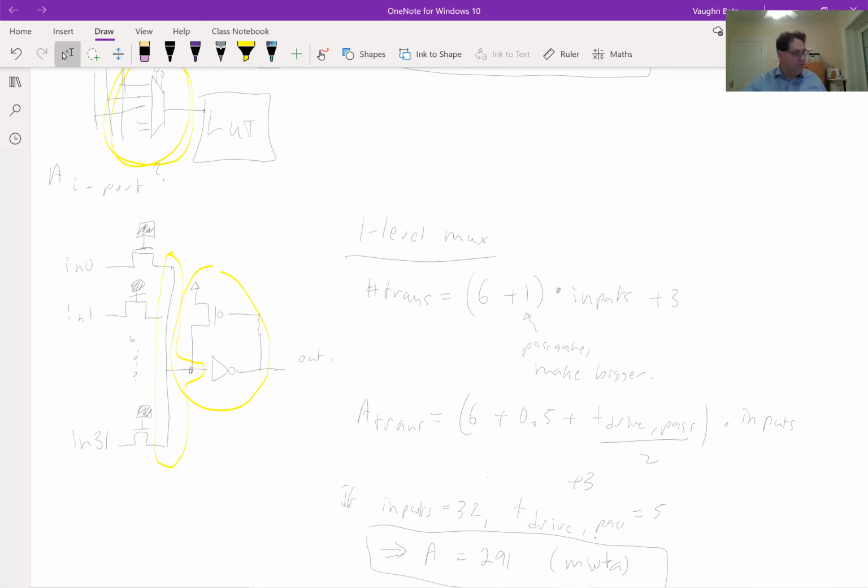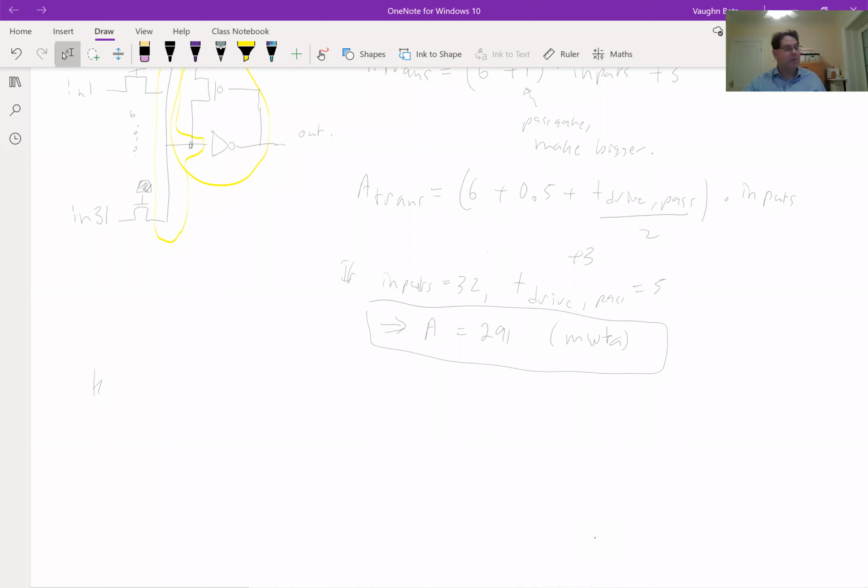If you want an FPGA that's simpler to design, sometimes it's done for embedded FPGAs where you're going to integrate it into a larger SoC. So it's not Intel or Xilinx FPGAs, but you might buy from Flex Logic, for example, an FPGA that can be integrated into a larger SoC. And there's some advantage there to using simpler circuit design styles. So they might do it with logic gates. But for the big FPGAs that are custom manufactured, pass transistors will save you a lot of area.